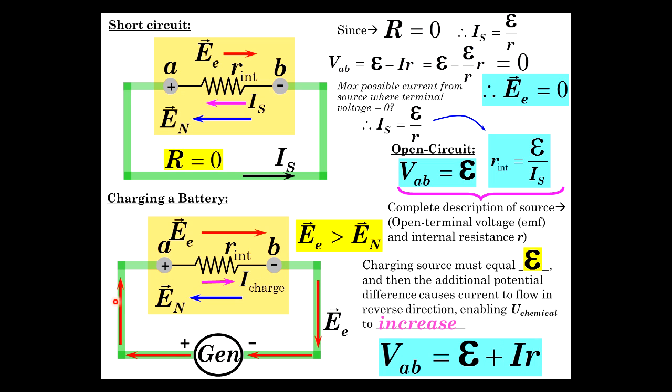So if you put a battery charger on a battery and look at the voltage, you will see, like for instance a car battery, approximately 13 volts sitting there by itself. You put the generator on, or the battery charger, and you'll see the terminal voltage go up to 14 or even 15, depending on how hard the battery is being charged.